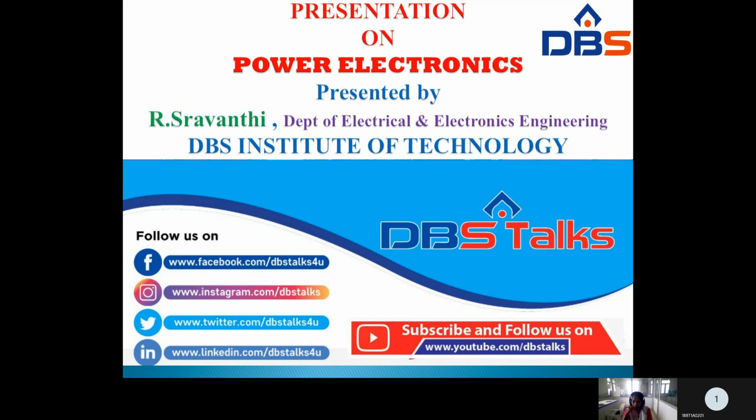A sinusoidal current flows through the resonant LC circuit, charging up the capacitor as negative at the end of the half cycle. This current will be reversed and flow through the SCR in opposition to the load current for a small fraction of the negative swing, till the total current through the SCR becomes zero. The SCR will turn off when the resonant circuit current is just greater than the load current.